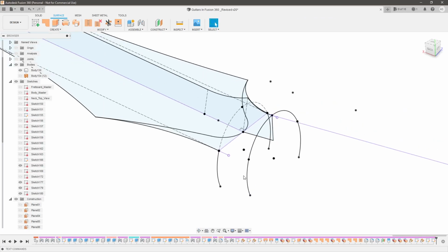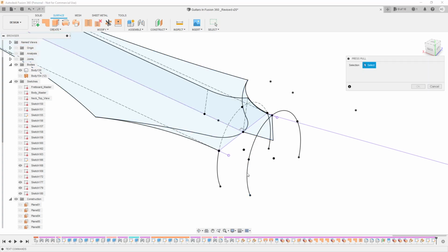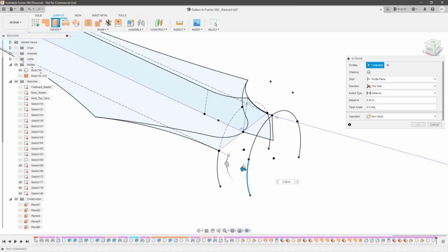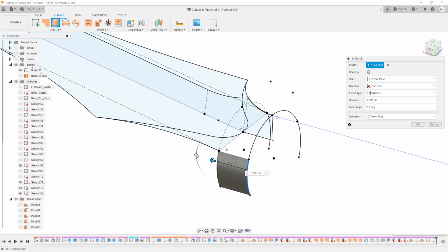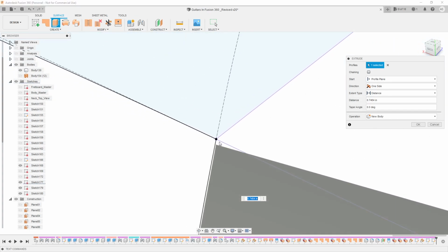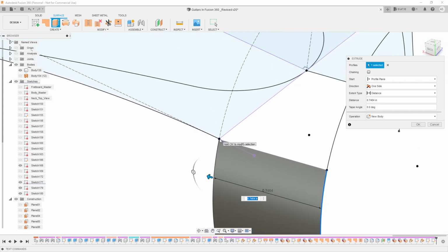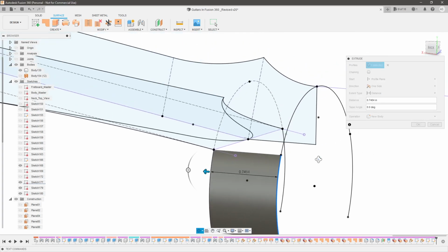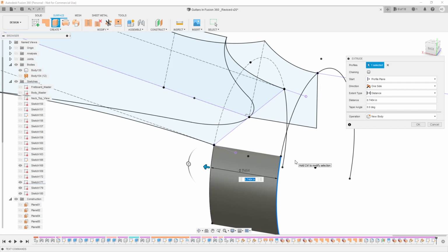One last thing I want to show you before we actually extrude or loft or patch anything is one addition I've made to this process. Before, I just extruded this surface, so let me grab that. I just extruded that up until this point. But you'll notice if you zoom in on it really closely, it doesn't actually touch the nut line. That's because it doesn't take into account the neck taper angle. And that's a problem a lot of you ran into.